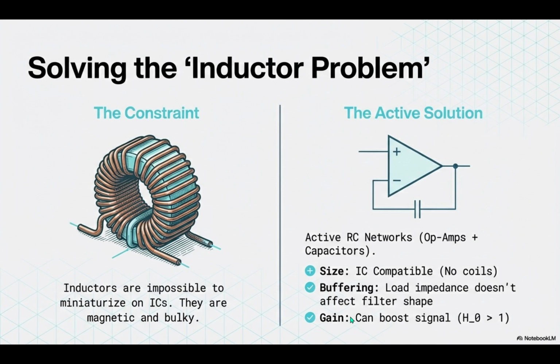Yes. Think of an op-amp as an interpreter. It listens to the filter with effectively infinite impedance, so it doesn't draw any current, it doesn't load the filter at all. I see. But then it turns around and shouts the message to the next stage with basically 0 impedance. So it creates a wall, the filter doesn't know what's connected, and the output doesn't mess with the filter. Exactly. Isolation. We can finally treat circuit blocks like Legos.